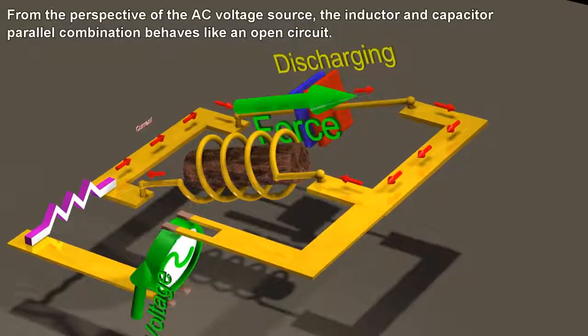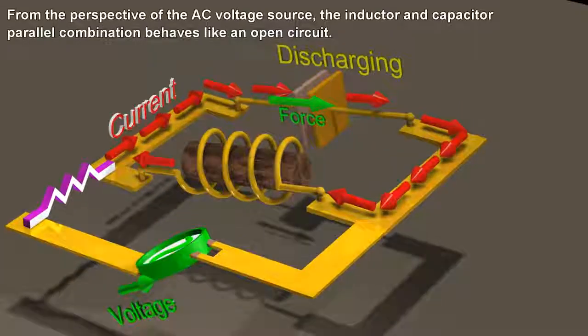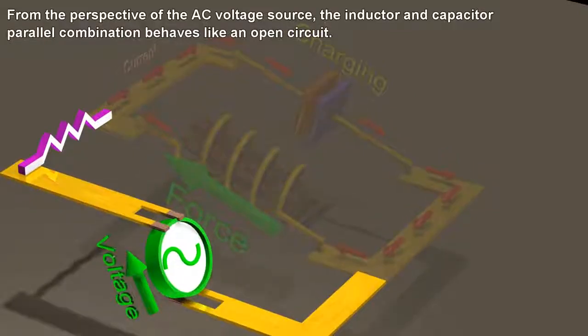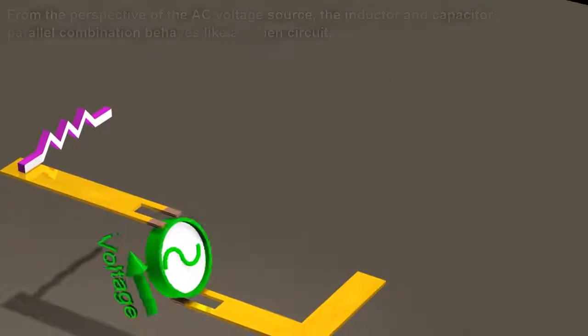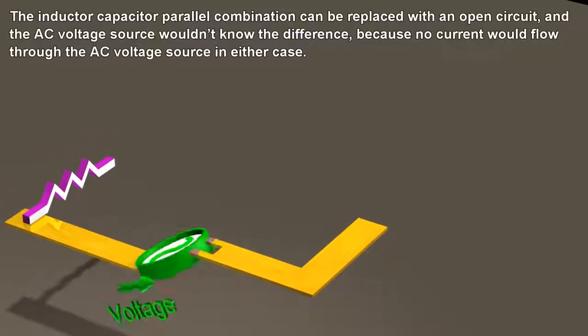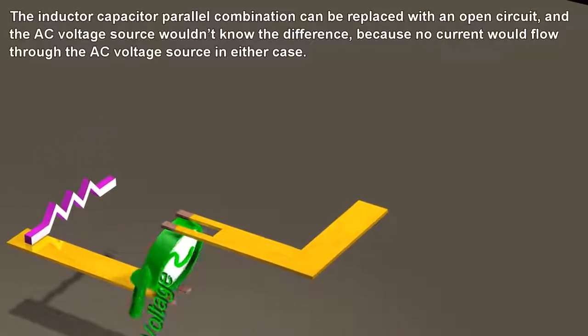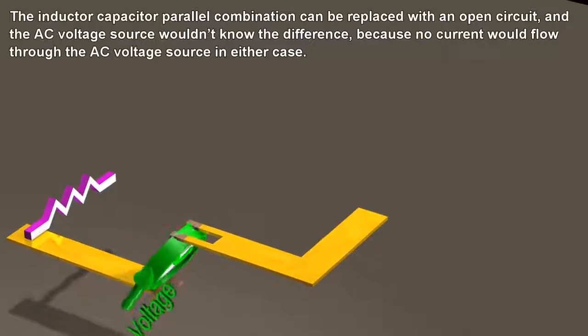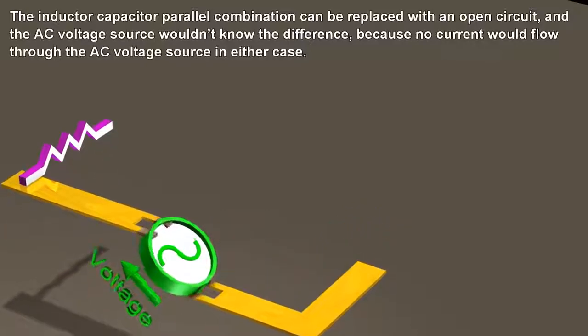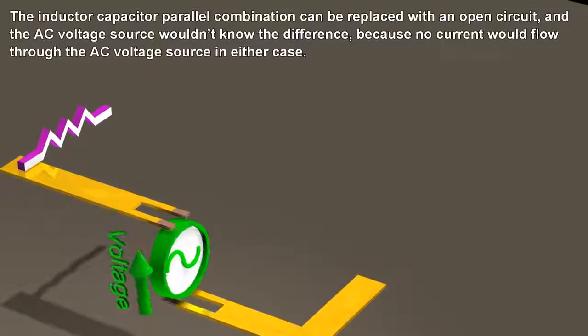From the perspective of the AC voltage source, the inductor and capacitor parallel combination behaves like an open circuit. The inductor-capacitor parallel combination can be replaced with an open circuit, and the AC voltage source wouldn't know the difference because no current would flow through the AC voltage source in either case.